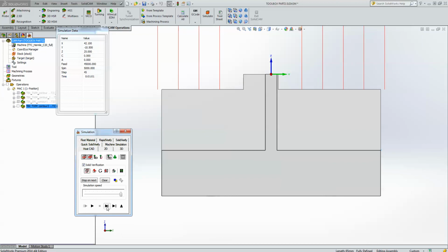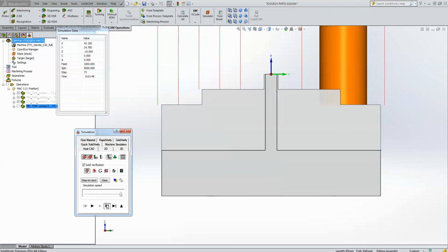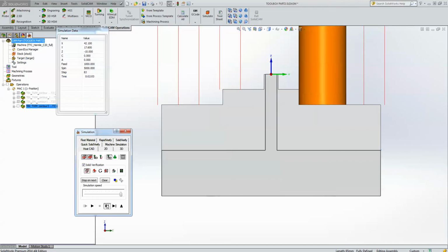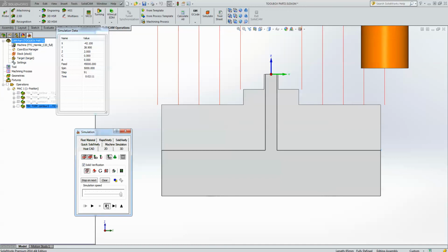Now the first step is not as critical as you go further down. So right now we go practically up until the wall itself, until the actual offset that I left over there. Now as I continue down, it goes down now to the next step. Now in this next step, look what happens. It's going to do exactly what it did before, but this time, note, it didn't go all the way to the end over here. Instead, it went back out over here. So we actually have now more support towards the wall.